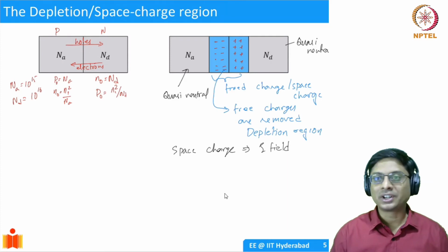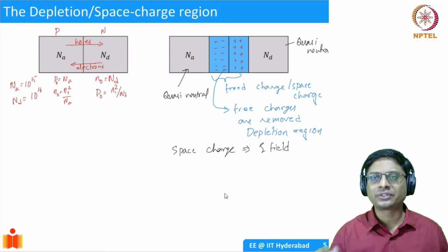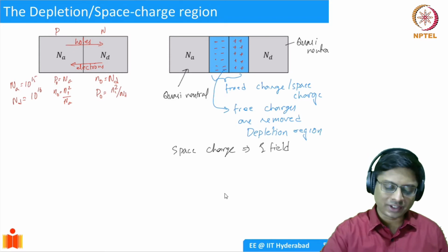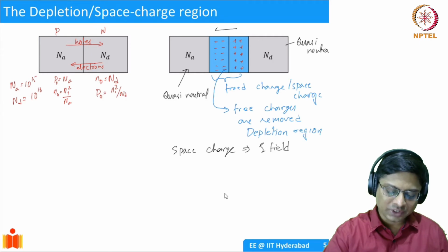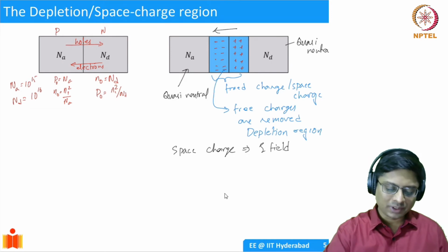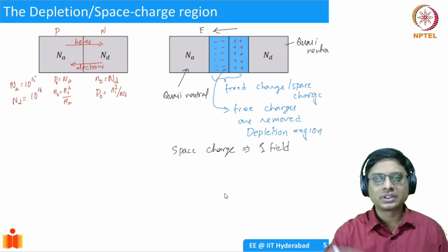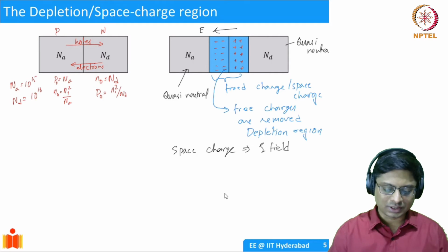This is very, very important to understand semiconductor devices. Whenever you look at any charges, look at what direction the fields are, right? So now the field is going to be in the direction opposing x. Like if I take x from left to right, the field is going to be from right to left, because on the right, we have the donor atoms, and those are positively charged, right? And on the left, you have acceptors which are negatively charged. So, yeah, right to left.